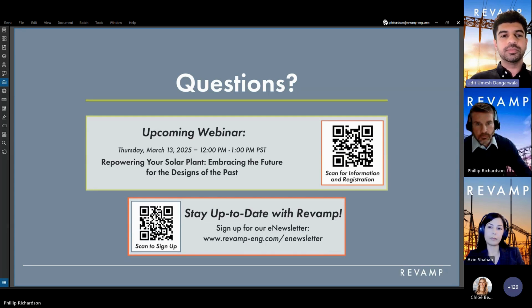However, we always recommend that to get an actual sense of harmonics within the system, it is good to perform a post-generation study where we get the data measured in the field and then process it to calculate the overall harmonics. I hope that answers the question.